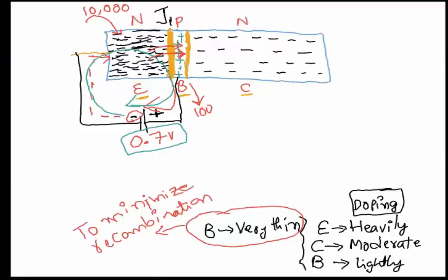There is always a requirement in transistors on how much base current you need to supply to forward bias that junction. As long as the voltage is above 0.7, you have enough voltage to forward bias the junction. So that's the first junction. It must be forward bias, meaning that the base should get 0.7 volts compared to the emitter side.